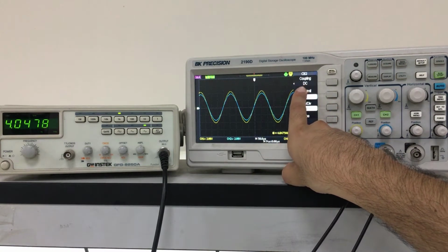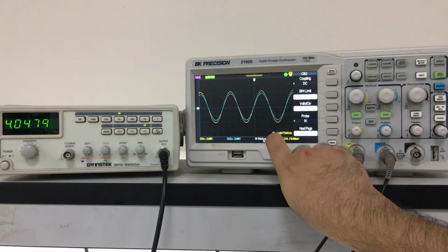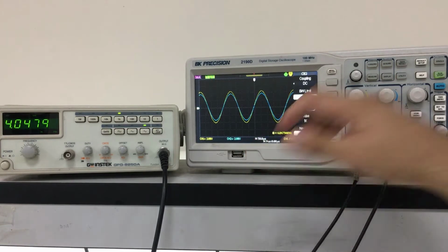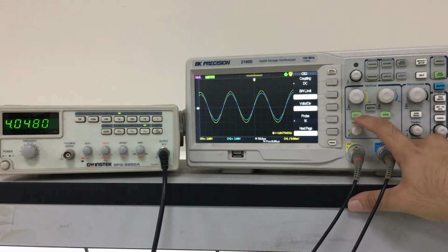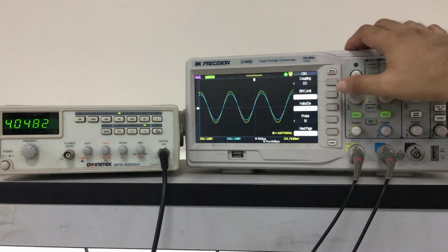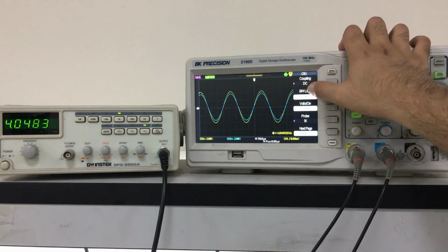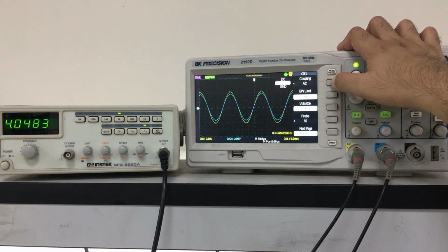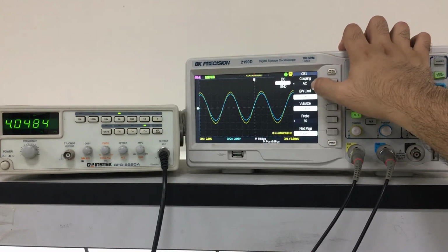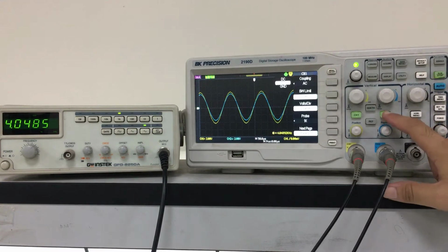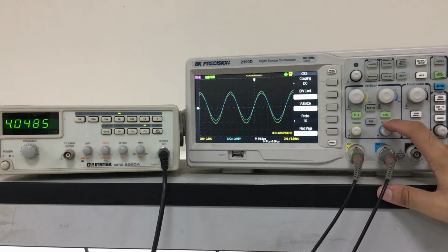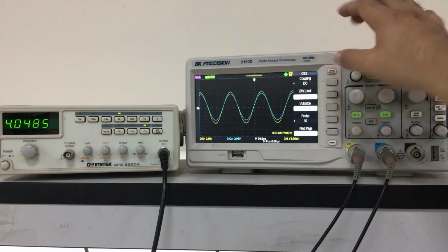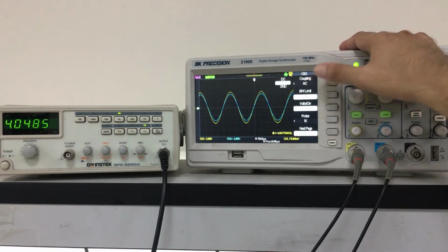This should be changed to AC for all experiments in EEE 241L. So how you can change it is press the channel button, channel 1 or channel 2. If I press channel 1, I'll get this menu. For coupling, press this button once and it will become AC. Now move on to channel 2, press the channel 2 button, coupling is DC,